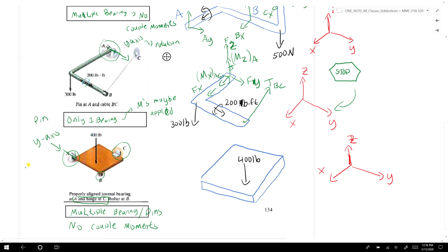All right, so you can look at the table if you're getting confused about how I'm determining the reactions and how they're directed. But if we look at the table, it would resist motion along the x-axis. So I'll write AX as a reaction force and would prevent translation on the z-axis. So I would say AZ. Right? And then we have a roller at B. So a roller will always apply a force normal to the point of contact. So you can write that force as NB.